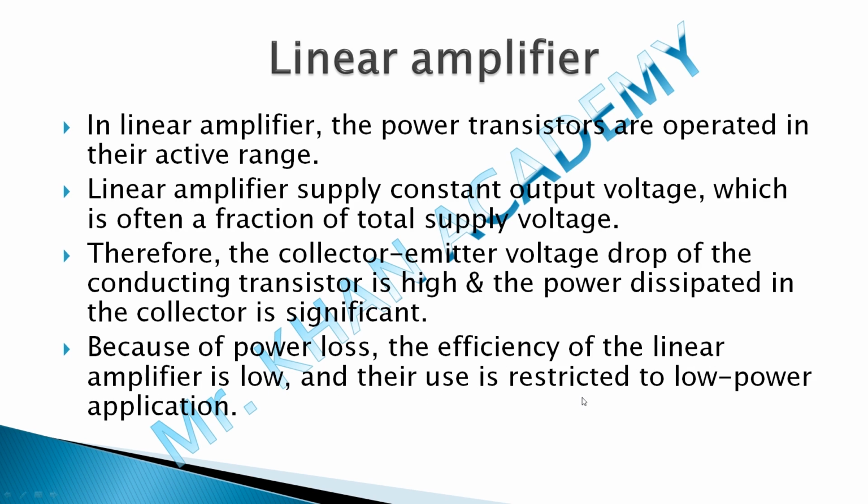Their use is restricted to low power amplifiers. As the drawback, as voltage drop increases, heat dissipation increases. Because of that, we only use the linear amplifier for low power, not for high power. As I'm using low power, definitely heat dissipation will be low. That is the advantage as well as the disadvantage of the linear amplifier. The circuit design and implementation are simple, but losses are high.